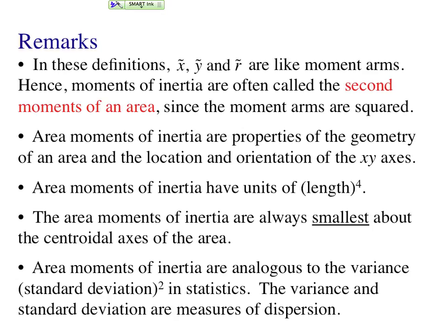How do we make this as large as possible? Our definitions for area moments indicate we want as much material as possible as far away from the origin of the coordinate system. An I-beam consists of two flanges spaced far apart by a connecting web.